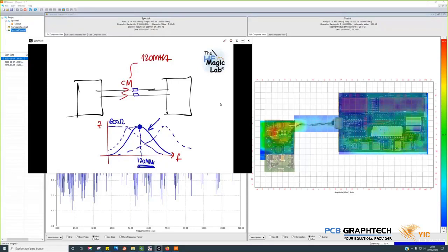If you look, this impedance has two parts. The first part is the resistive effect. The resistive effect of this ferrite is doing something like this. And the other effect that I am going to plot in pink is the inductive effect. No? So this is what we call X, the reactive effect, and this is what we call the resistive effect.